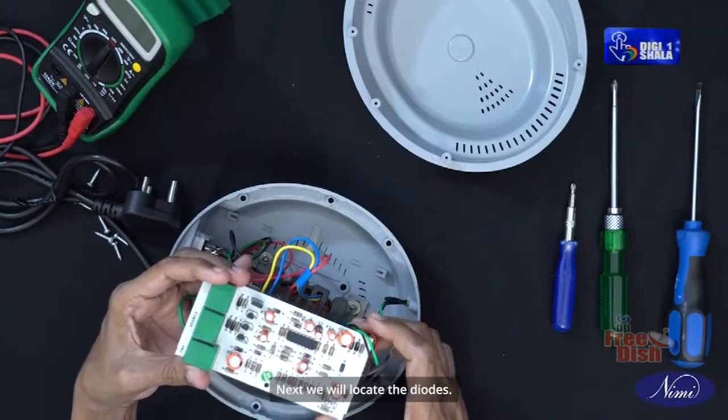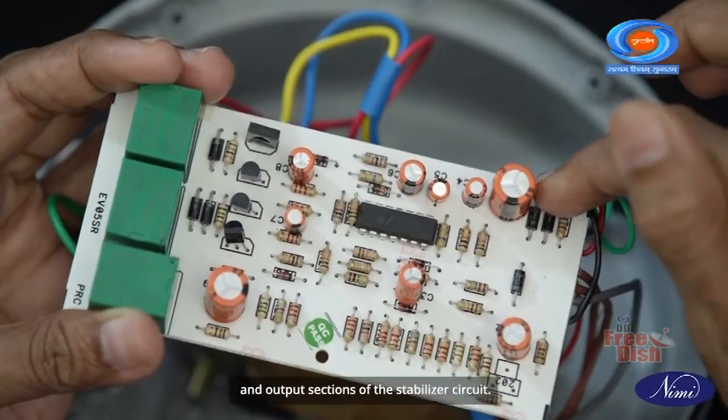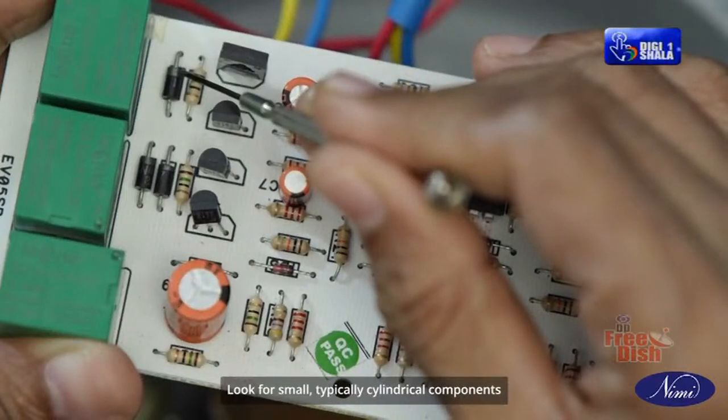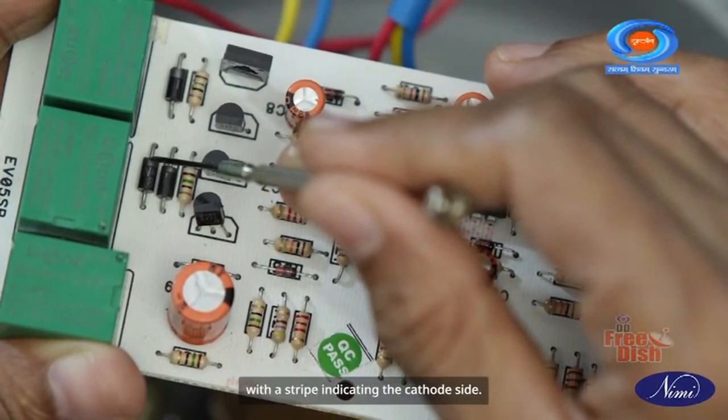Next, we will locate the diodes. Diodes can often be found near the input and output sections of the stabilizer circuit. Look for small, typically cylindrical components with a stripe indicating the cathode side.